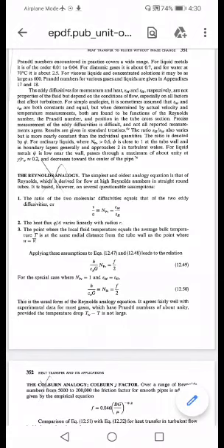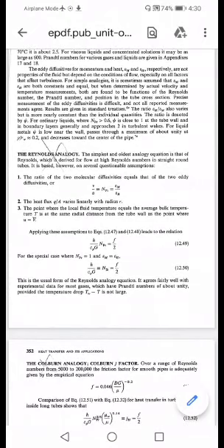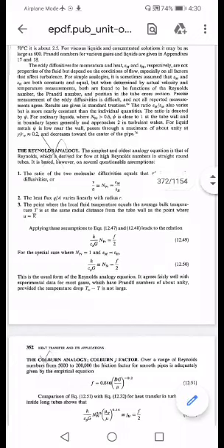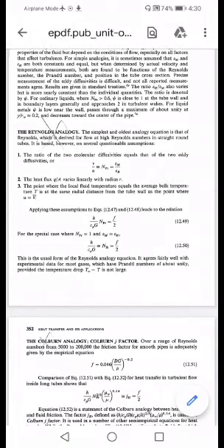Now by taking the ratio we are getting the Prandtl number, and we are going to correlate it with the Prandtl number and the Stanton number, where h upon Cp into G into Npr is equal to f upon 2, where f is the friction factor. You might remember the Fanning friction factor in our fluid mechanics, in the second chapter, section second, where we have seen f is nothing but friction factor.